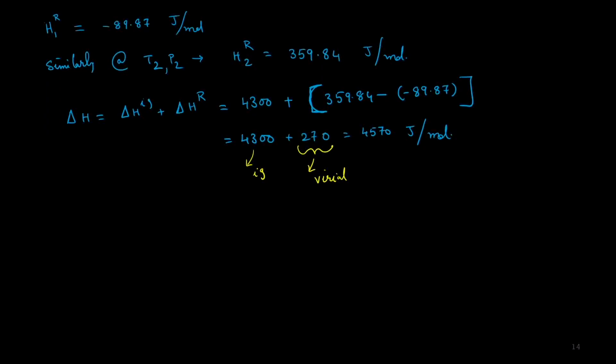And for a process, that is a lot. If it is an energy requirement for a process, then it's essentially 6% more. So these corrections are necessary for process calculations depending on how far away I'm from ideality. And we can accomplish this by using the residual properties and an appropriate equation of state. In this example, we have used the ideal gas equation of state.